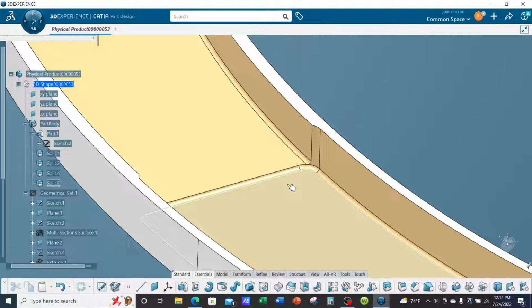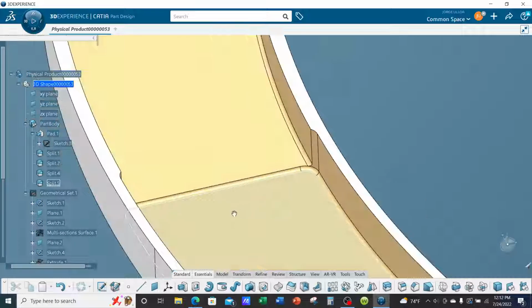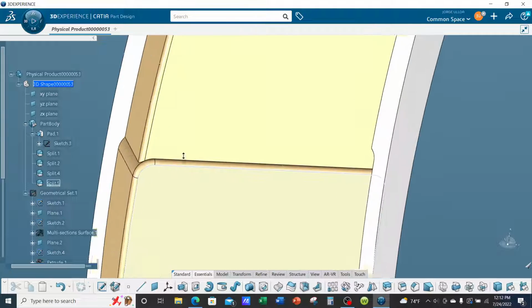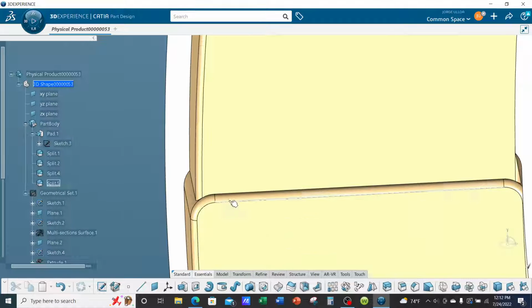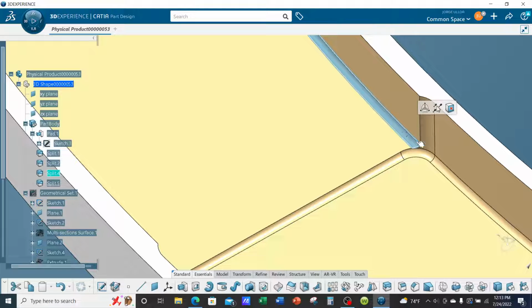Same thing with web. So flange, web. So here it's 1/2 inch thick. Here it is 0.375. And same thing with the other flange on the opposite side. It started off at 1/2 inch thickness and it went down to 3/8 of an inch, 0.375. And we have our fillets. So this was our 1/2 inch fillet, radius of 1/2 inch. Again, typically you want to go a little bit larger than the size of the end mill. And we have our 1/8 inch radii, just like we have here and here.